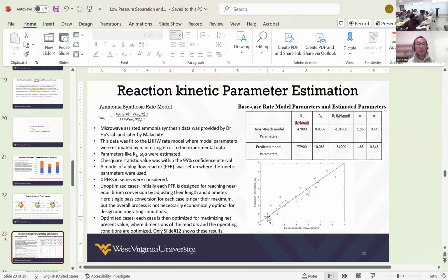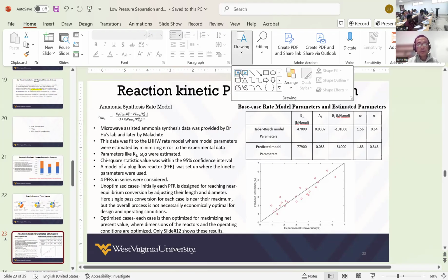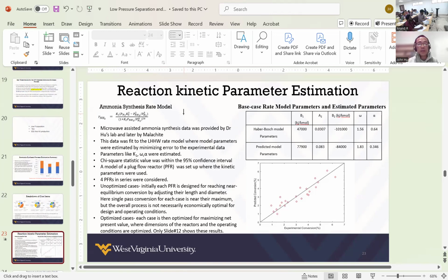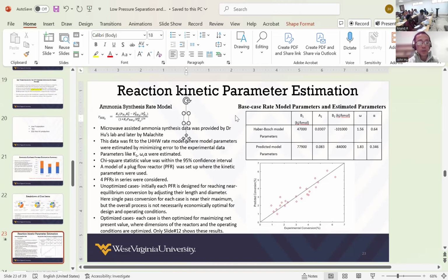You could scale up linearly with the data. But in the real engineering world, you have to have the reaction kinetics. You have laboratory data and you develop a kinetics curve in order to estimate the reactor size. This is the reason in the classroom I showed you the specific activity.